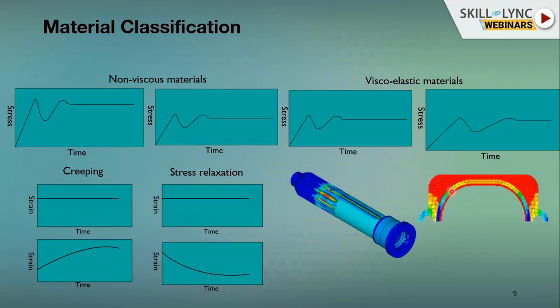This is happening because of the seal, or you can even call it a washer in general language. That washer is a kind of medium used to prevent the leakage, although there is a whole lot of pressure on the other side, because your water is of constant supply when you have the water in your tank at home. So when the seal starts deteriorating, you get such kind of leaks.